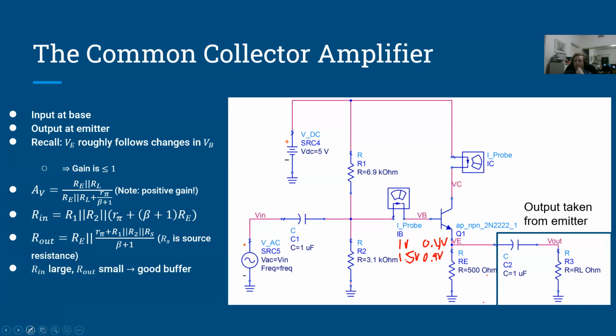You might ask, what's the point if you have a gain of 1? Didn't we want a high gain? No, a low gain, and 1 is pretty low. You might as well just feed your signal straight through and bypass the amplifier if you're not amplifying it. And the answer lies inside the input and output impedances of this amplifier.